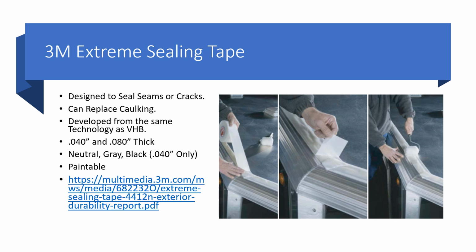This is very beneficial for a trailer manufacturer, because once they put the extreme sealing tape down, they can move the trailer to the next step in the manufacturing process, creating faster throughput. Whereas using caulking, they have to wait 24 hours for that sealant to cure before they can take that next step.